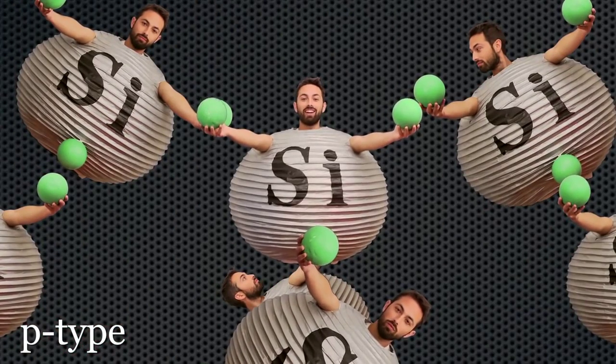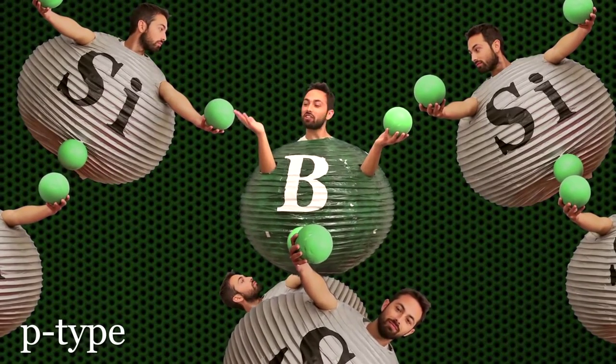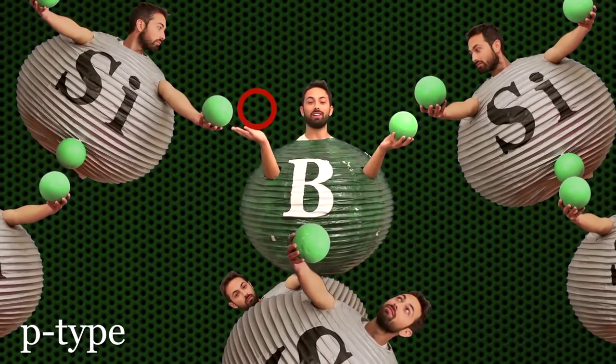In P-type doping, an element with only 3 valence electrons is added to the lattice, like boron. Now this creates a hole, a place where there should be an electron, but there isn't. But this still increases the conductivity of the semiconductor because electrons can move into it. Although it's the electrons that are moving, we like to talk about the holes moving around because there's far fewer of them. Since the hole is the lack of an electron, it actually acts as a positive charge. And this is why P-type semiconductor is called P-type. The P stands for positive. It's positive charges, these holes, which are moving and conducting the current.